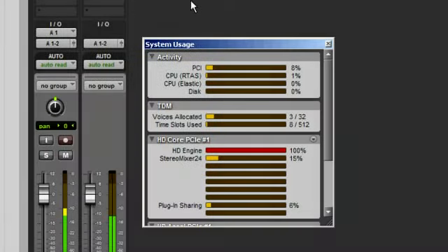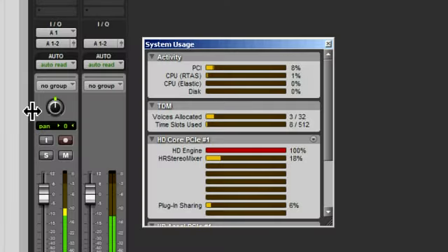Let's take a look at the 4 different mixing engines of Pro Tools. First off, we have the basic 24-bit stereo mixer. All audio signals that went through the 48-bit double precision Pro Tools mixer will be truncated to 24 bits eventually. The dithered stereo mixer gives better sounding results by applying dither to lower the 48-bit mixer resolution down to 24 bits. Please note the higher DSP usage.